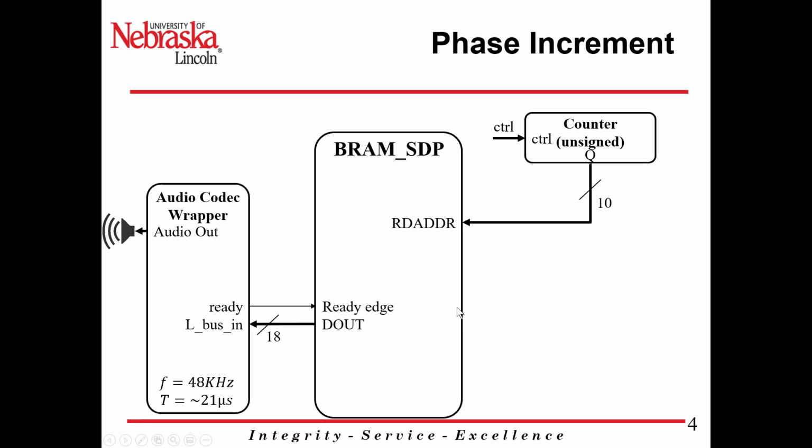So you're going to initialize your VRAM with this sinusoidal waveform, and in Lab 4, you're actually going to utilize other waveforms other than the typical sinusoid. So we'll show you how to do that, and then we're going to create some other waveforms like heartbeat or nonlinear waveforms. That would be the requirement.